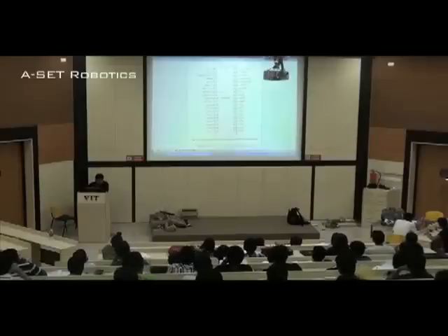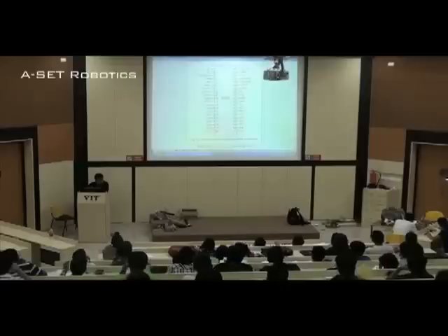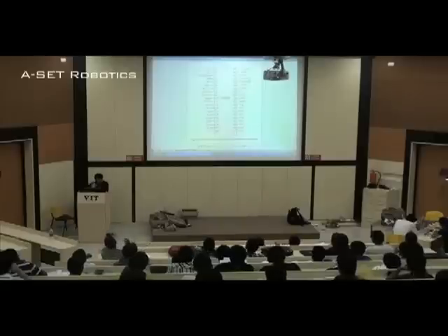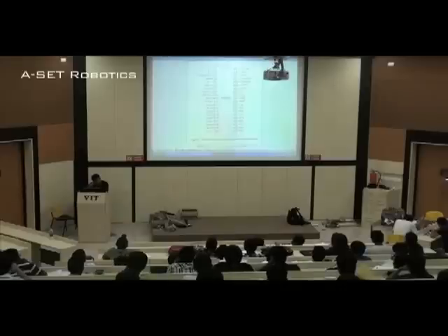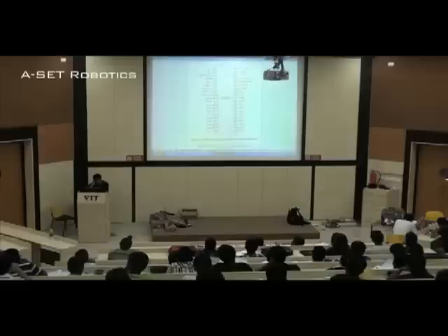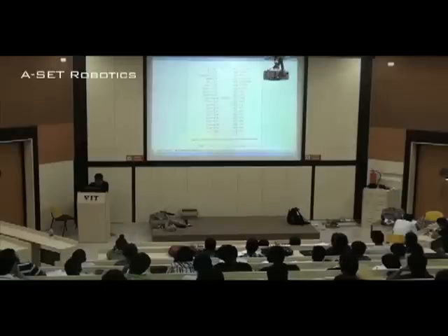That means it is sending a signal out, right? INTR, the request, would be given by devices, and the acknowledgement would be given by the microprocessor to the devices. So INTA would go out of the microprocessor and INTR would get inside the microprocessor, correct? Getting my point? And now you'll say, why is this inside and out?